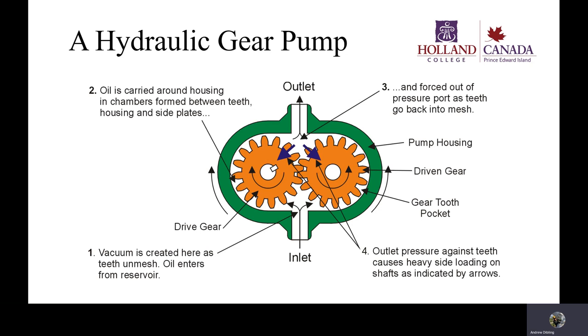As a result, this hydraulic gear pump will be about 90 to 95% efficient, which means that if I'm moving 10 liters of oil, a half a liter is seeping back into the inlet for lubrication and cleaning and things like that. That's not a bad thing at all. You're still getting a 90 to 95% efficiency out of the machine. And in any industrial machine, 90 to 95%, that's pretty darn good. This is old technology. It's simple technology. It's really easy to maintain.